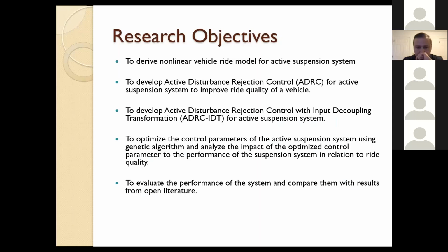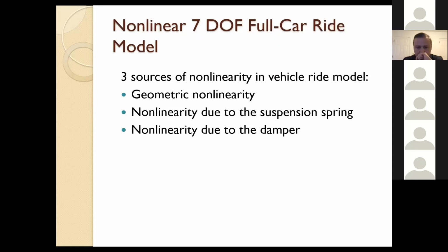So the objective of this work, basically, number one, is to derive a nonlinear vehicle ride model, which I will explain why we are interested in this. After this, we develop an ADRC model, and an ADRC model with input decoupling transformation, which is called ADRC IDT, and compare these two for the performance of the suspension system compared with the passive performance. And based on this, we'll evaluate the result as possible.